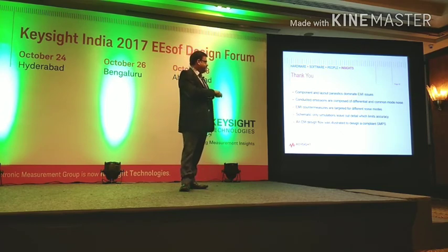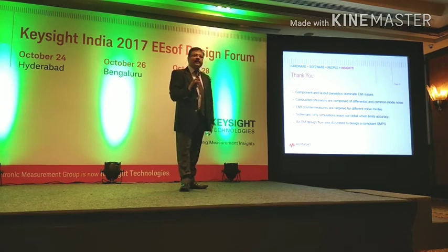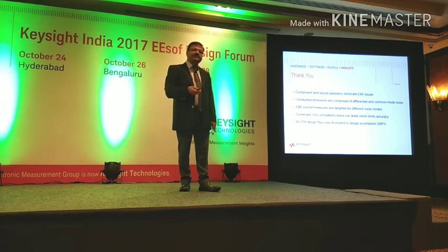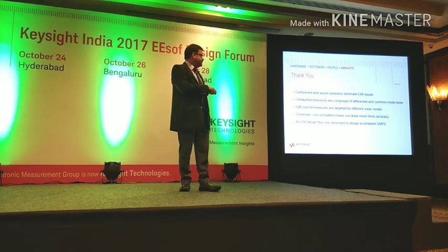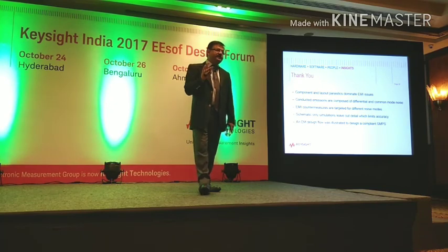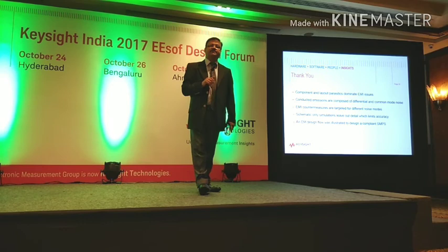Schematic-only simulation is not sufficient because it leaves out detail which will limit your accuracy. So you can't really predict what will happen in real life once you make this converter circuit and test it. And the EM design flow was illustrated in this short presentation to design a compliant SMPS with the CISPR 25 Class 5 specification. So I'll stop here and look at questions, if there are any.